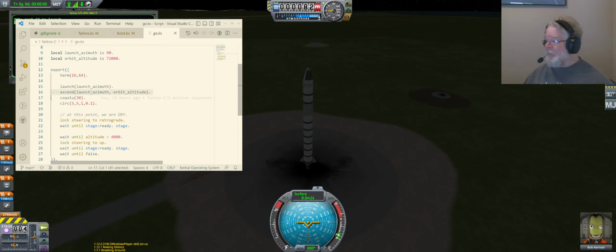Now we're overpowered, so we're going to be thrusting more than you normally need in a gravity turn for efficiency. Over the long run, I think you get better craft efficiency if you're full throttle, but your thrust to weight ratio is low. Maybe Scott Manley worked out those numbers. I don't know. I just overthrust and get there, and I end up coasting up from 35,000 or 40,000 meters. So here's the coast. Coast U will coast upwards until you're within 30 seconds of apoapsis, and it will stop when you're within 30 seconds or if your altitude is starting to descend.